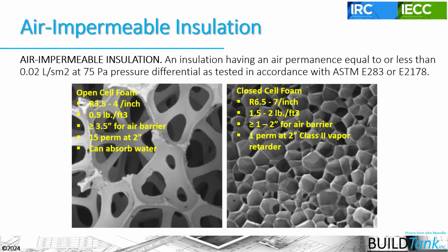And we'll go into vapor retarders in much more depth in another presentation, but we need to understand that vapor retarders and air barriers, or air barriers and vapor barriers, are not the same thing. They're achieving different characteristics and performing different functions, but there are some materials that can be an air barrier and a vapor retarder in the same product.